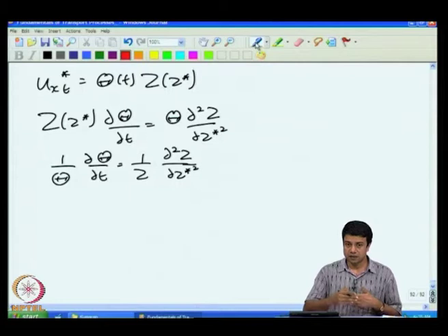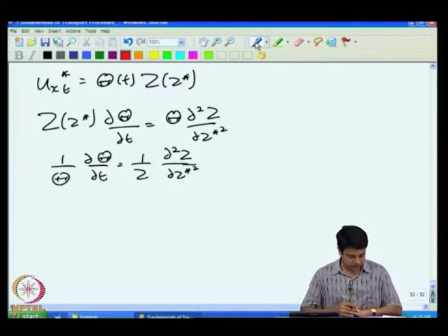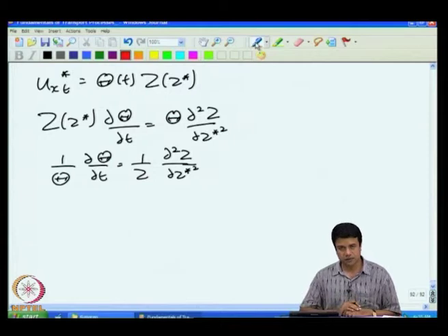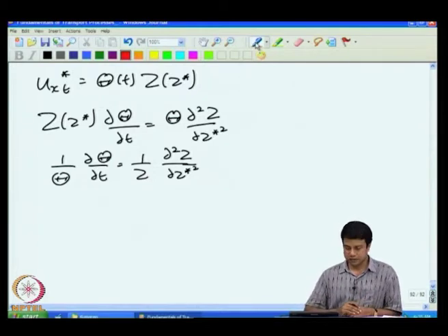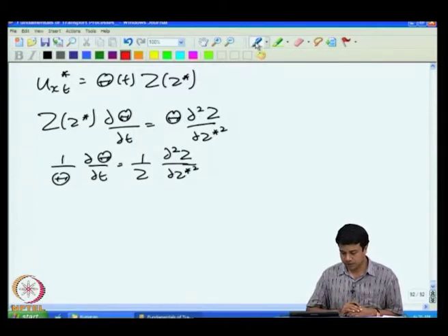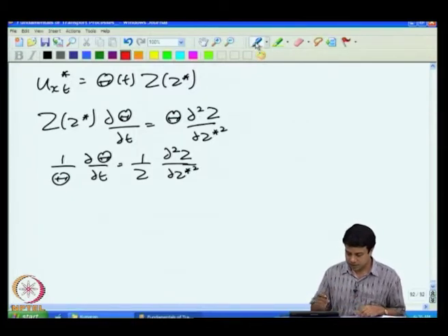Okay. However, when we subtracted out the steady part, for the transient part alone we had temperatures equal to 0 on both surfaces. A similar reduction gave us homogeneous boundary conditions on both surfaces. A similar reduction has to be done when there are inhomogeneous terms in the equation as well, due to sources, sinks, body forces and so on. Once that is done, then I can set both of these equal to constants.